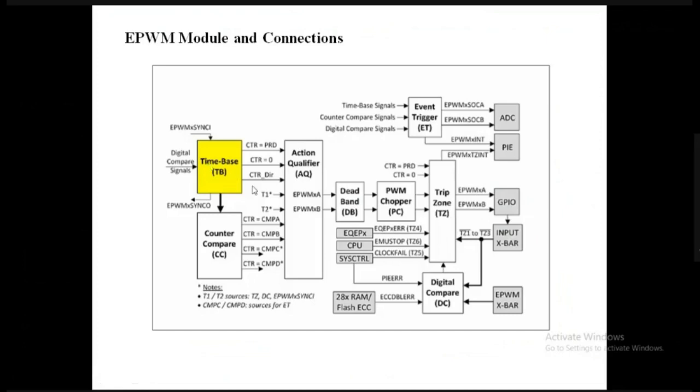From this time-based submodule, you can see that the EPWM sync-in option and sync-out option are connected over here as well. This time-based submodule will be present in each EPWM module. Like this is one EPWM module, and like this there are 12 EPWM modules that we saw. Into this particular EPWM module, these are the submodules. Now there are certain functions or tasks that these submodules are assigned to do, like counter compare, action qualifier, and this time-based counter.